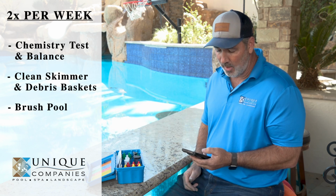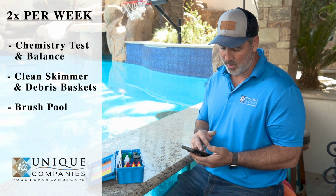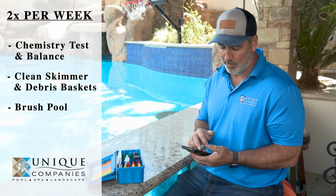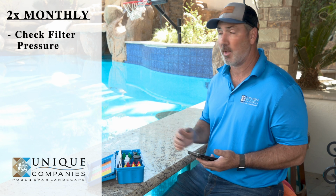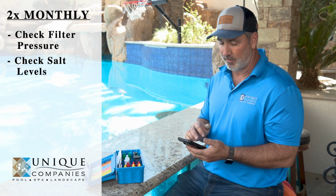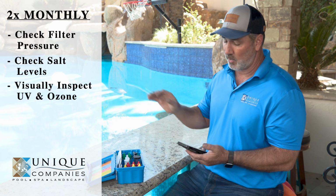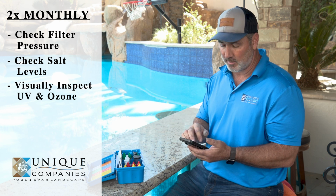So back to the proper water increments, but brushing the pool a couple times a week is ideal. Twice a month, we ask for you to check the filter pressure. We'll go into that when you look at the filters and pumps, to check your salt levels, visually inspect your UV and ozone status for some of the blue lights.